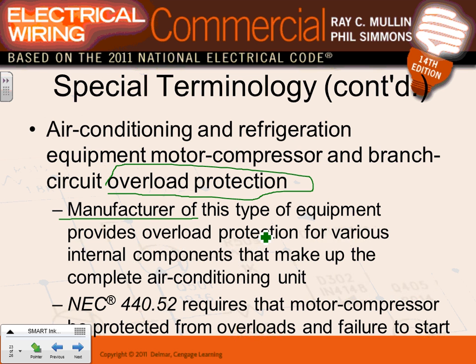Why do you think they provide the overload? Because the compressor, guys, has a lot of things. There's a compressor motor and all these relays and controllers and transformers that step down to control voltage. So there's more to it than just a fan. So they provide the overload. Article 440.52 requires the compressor overload protection and failure to start. That's what provides overload protection and short circuit protection for your system.